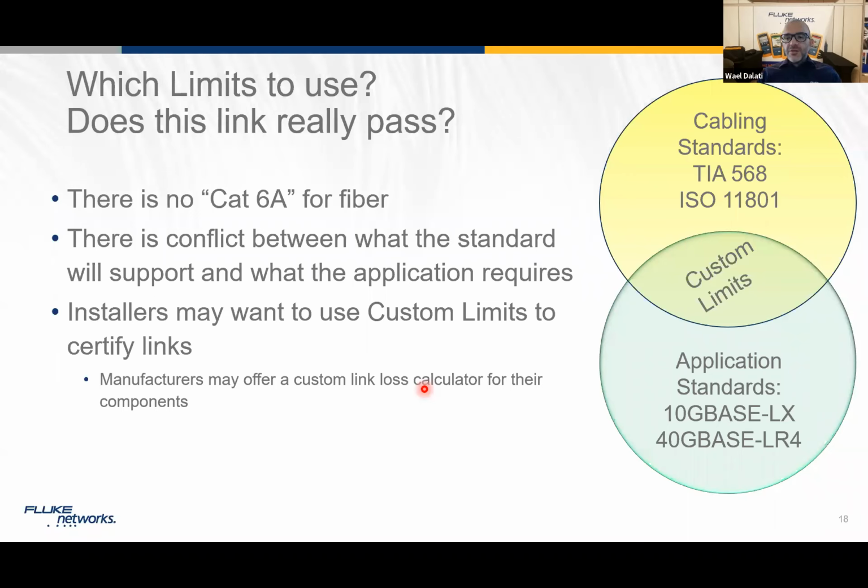This mismatch is causing a lot of distraction in the market: which one do I use now? Do I use the application standard or the cabling standard? Some people say, you know what, I'm going to work out something in between those two, and I call it a custom limit, where I define what is best for my business in my testing limits. So that's why we now see a new trend in custom limits, and we've seen some vendors and cable manufacturers calling to test according to a custom limit, not according to cabling limits or application standards, because that's probably where the future is going to take us.